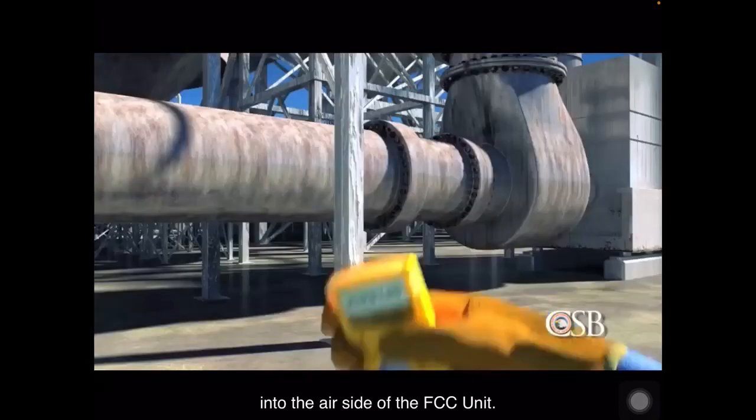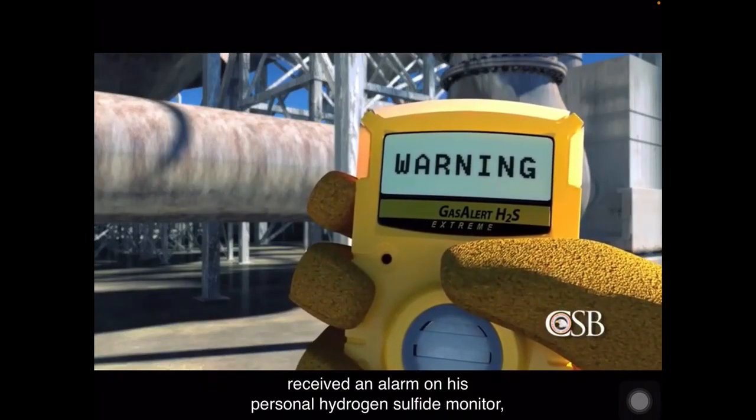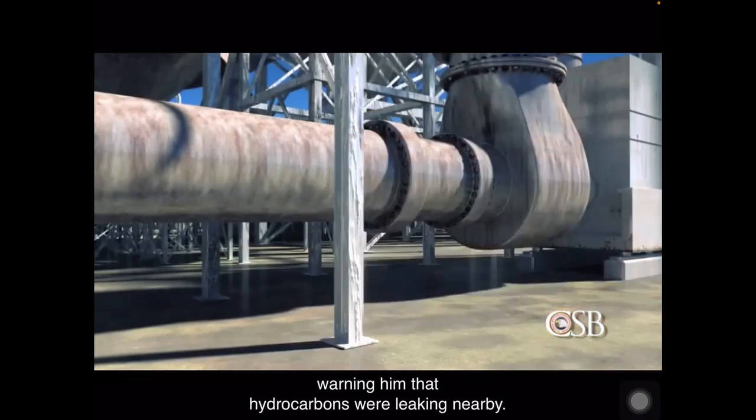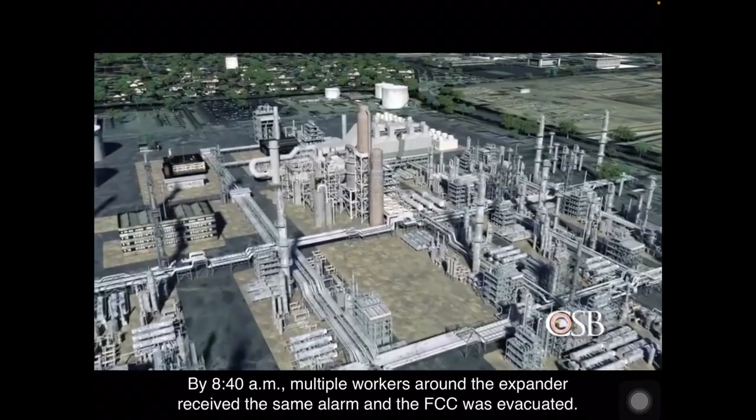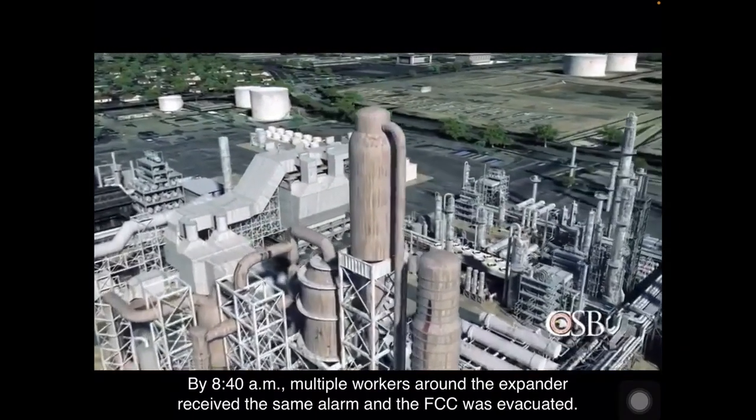The hydrocarbons flowed into the reactor, where they escaped through the leaking slide valve into the air side of the FCC unit. At 8:07 a.m., a maintenance supervisor working in the FCC unit received an alarm on his personal hydrogen sulfide monitor, warning him that hydrocarbons were leaking nearby. By 8:40 a.m., multiple workers around the expander received the same alarm, and the FCC was evacuated.